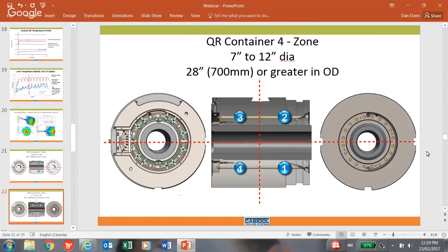During extrusion, zone 1 will be running between 85 to 100% of the time. Zone 2 will typically not run more than 5 to 15% of the time, where zones 3 and 4 will run 20 to 30% of the time, maintaining the natural cooling taper of the open-ended container. Obviously, these temperatures and rates change from press to press and from container to container, hence the reason for a Castool experienced technician to be on site during startup, and once again, once or twice through the year, to examine that the extrusion conditions have not changed.